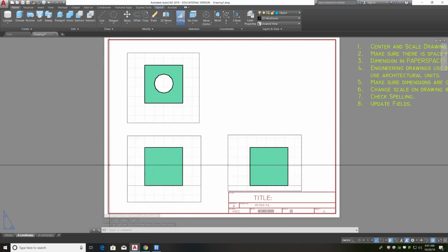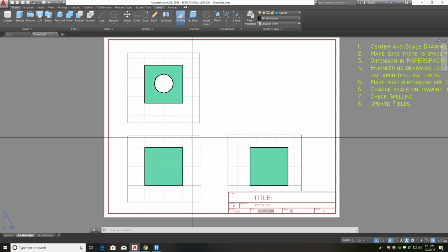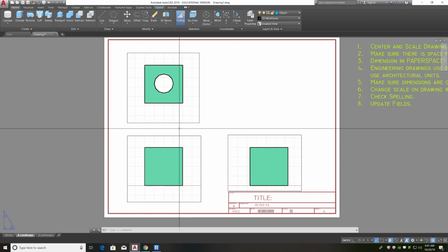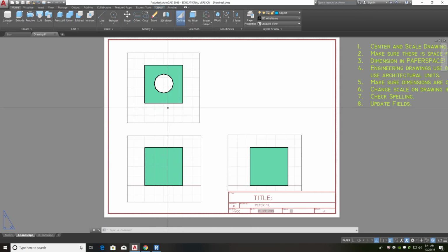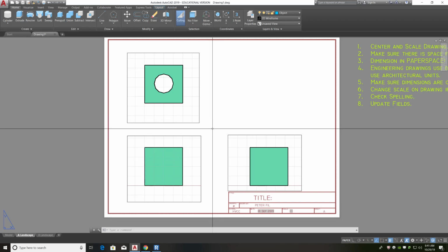All right, so I've laid out my 3D model using SolView. Now the only problem is that it's not really a proper 2D drawing. Okay, it's still a 3D model. I still see my visualization style. So what I'm going to do is use a command called SolDraw for solid draw. So SolDraw, and hit enter.